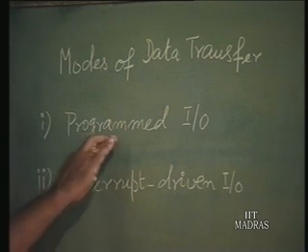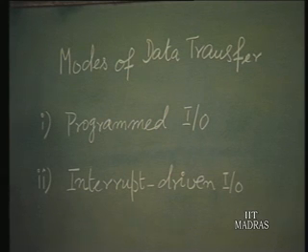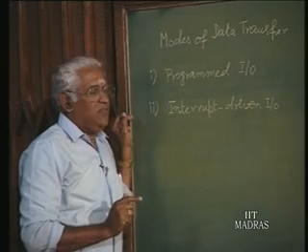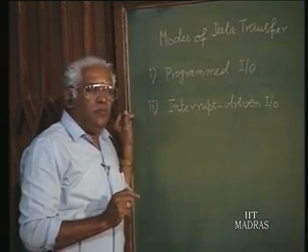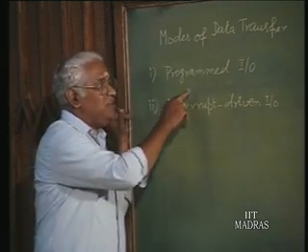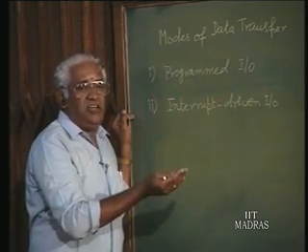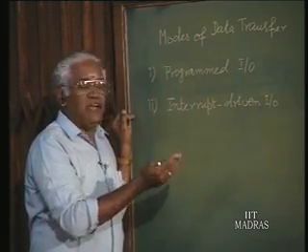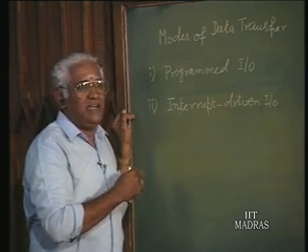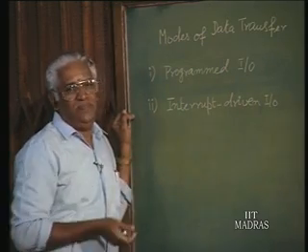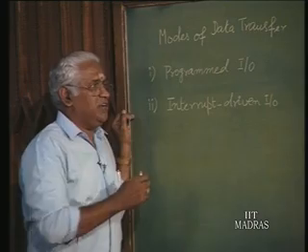The problem with that particular thing was, because it is at the CPU's initiative, as and when the device is ready, the CPU may not be aware of it, and hence it may not check the status of the device and know that it is ready, and so there is a possibility that the data could be lost. That is what it is.